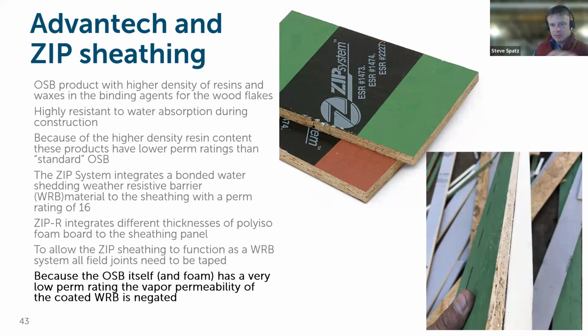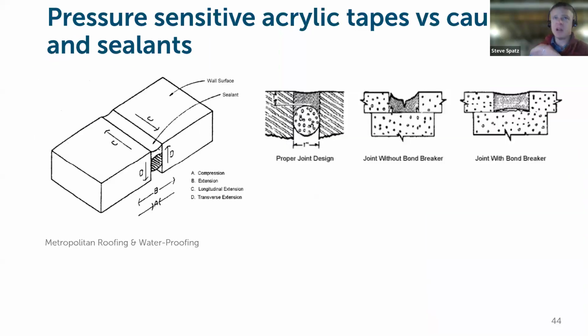I mean, that's hopefully what we'll iterate towards further in this, that the details really do matter. The key thing that I will say though, is that with the Zip sheathing, the big fundamental shift in process that occurred with it being commonly used is that people started taping their sheathing, which was never done before. When I came up learning how to put buildings together, I didn't tape sheathing as a common practice. So that became more uniform in addressing your sheathing layer of the building. That gets you a lot of the way there as far as the pressure boundary and air barrier goes, but it doesn't account for all the details.